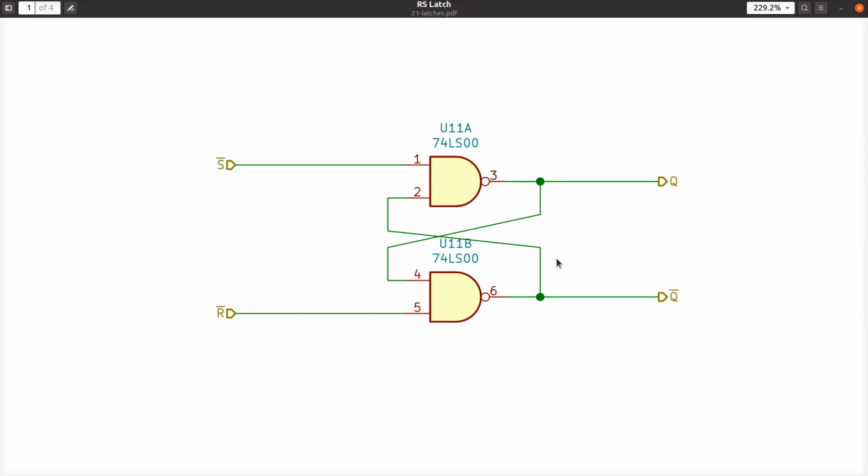All right? So those of you with a 5 gigahertz CPU, what that means is you're dealing with 1/5 of that, 6 centimeters is the distance that something can react to the CPU clock before the clock ticks twice. All right. Now, so what am I on about with all this?